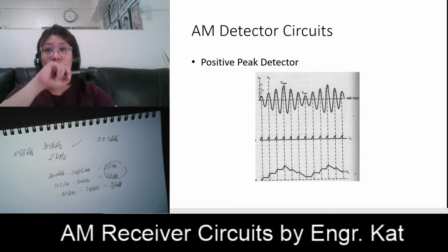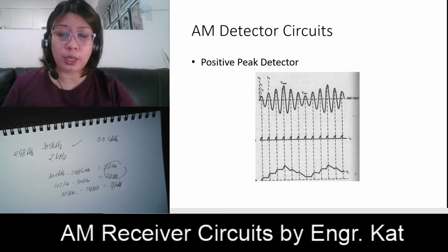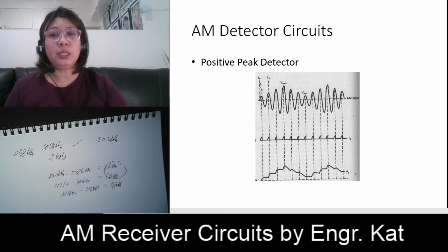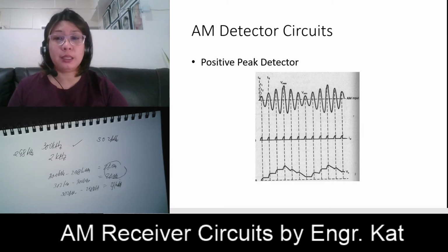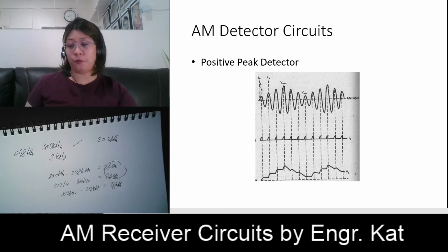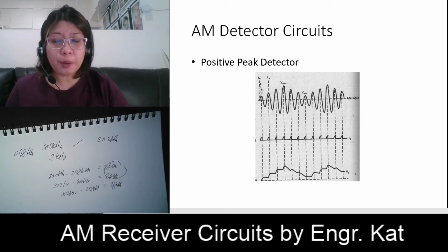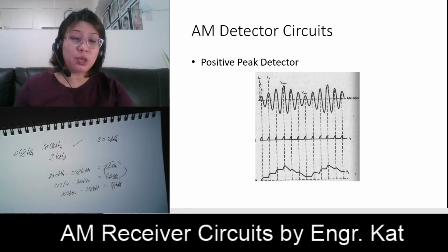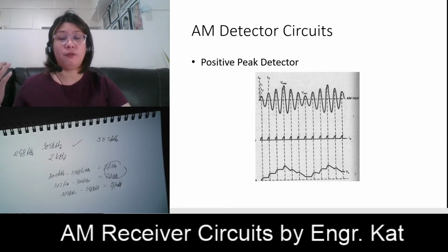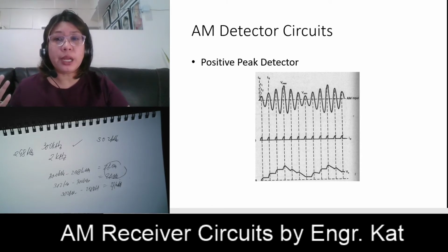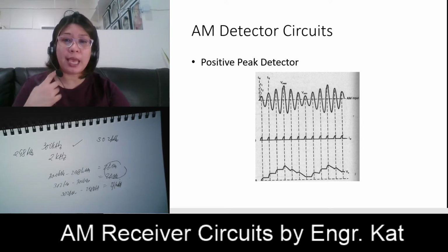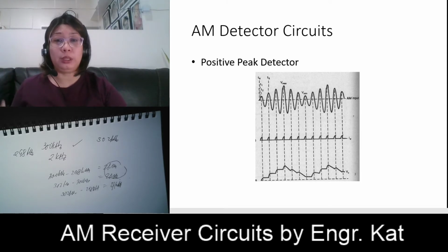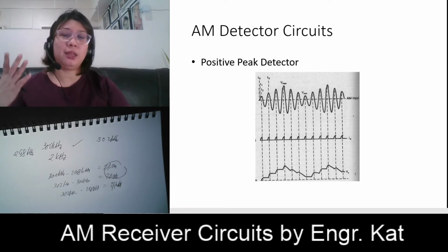This figure here shows three waveforms. This is the input waveform in the form of an envelope, this is your diode current waveform, and this is your output voltage waveform. So very simple, what is the purpose of your diode? At t equals 0, your diode is in the reverse bias mode, so it is not functioning. Therefore, our current ID is equal to 0, and if ID is equal to 0, we don't have an output voltage, and your capacitor is not yet charging.